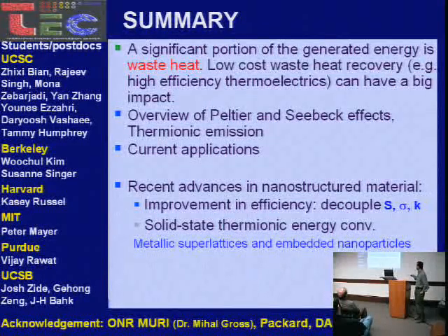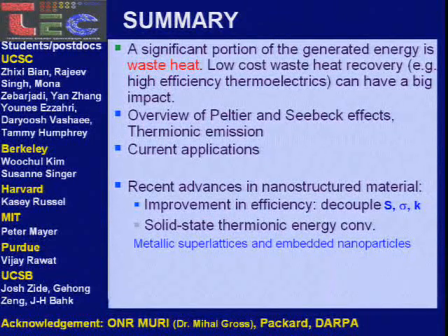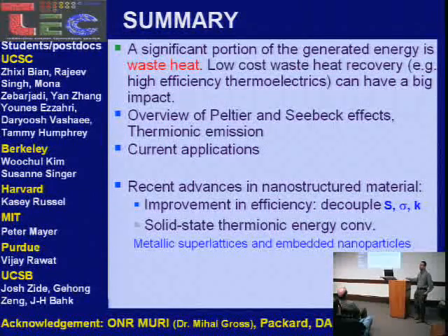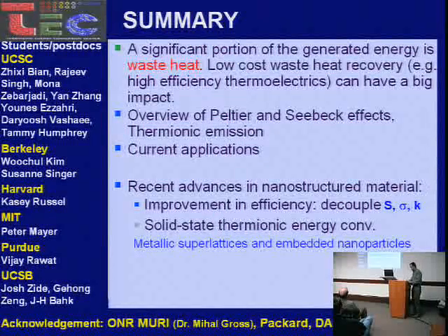Then I discussed a possible way of using Seebeck and Peltier effects as a solid-state energy converter, and showed some of the applications. But really, using nanoscale materials, when you can decouple the 3 material properties, Seebeck coefficient, electric conductivity, and thermal conductivity, that's the only time you can make a very good solid-state energy converter. Thanks for your attention.